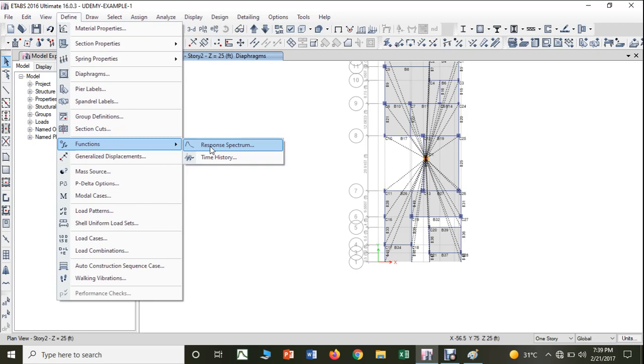That also we are supposed to choose. Okay, and not only that, you are choosing the building. No, you should know what is the importance factor of that building. That means you are supposed to know what type of material you are using, what type of building you are using, what is the use of that building. That also plays a very important role, right? So by considering those factors, we can do a dynamic analysis.